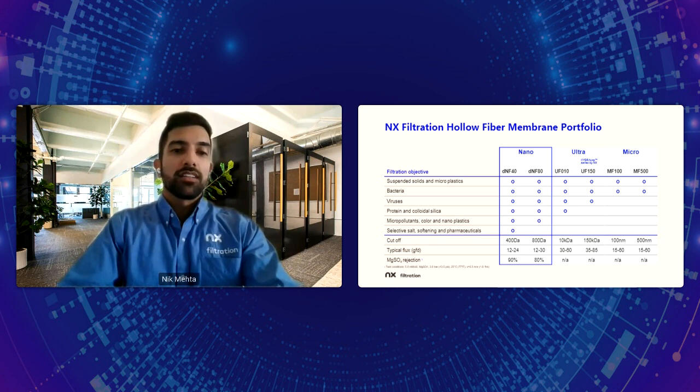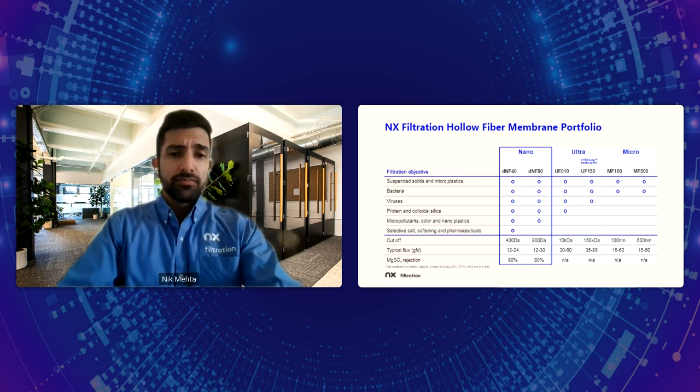So you can combine the advantages of multiple technologies, in addition to the fact that these are not polyamide based membranes like you might expect from a standard RO or spiral NF. For that reason, they have a much better stability in the presence of oxidizing solutions such as chlorine, allowing them to be cleaned with chlorine.